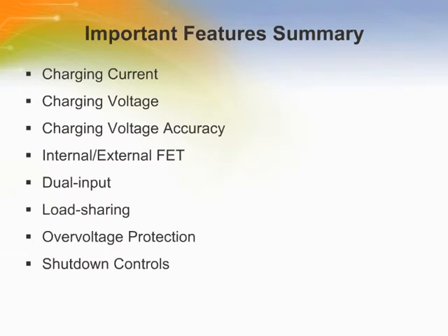A high-performance charger is required to recharge any battery quickly and reliably. The following system parameters should be considered in order to ensure a reliable and cost-effective solution. The charge current needed depends on the size of the battery being charged. If a battery has a 200 milliamp hour capacity, then having a 1 amp charger is too much, as its peak charging is 5C. If you remember from the previous slide, typical lithium-ion batteries are not charged at rates above 1C.